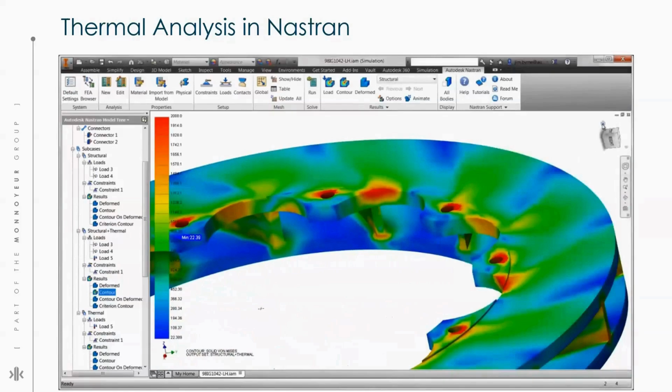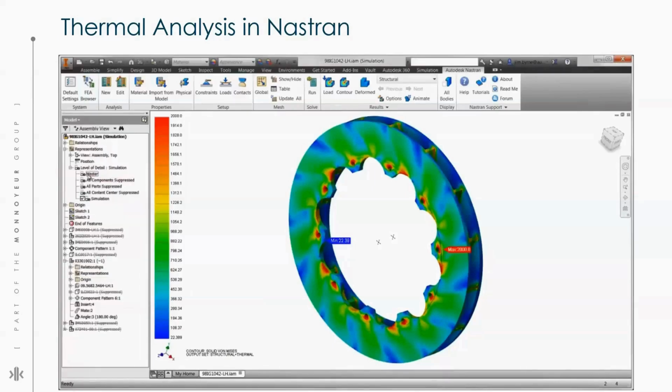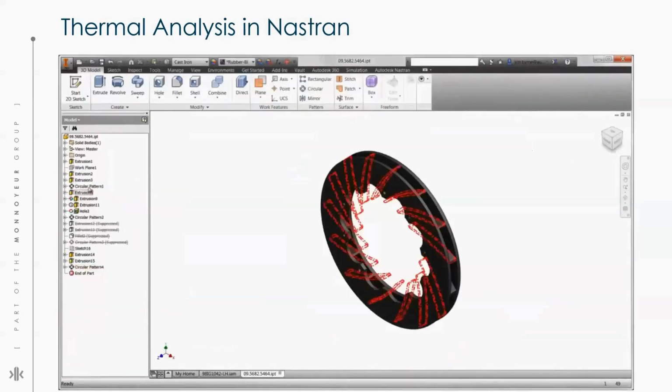The changes that we make here in Inventor can be reanalyzed right inside the CAD design environment. So you can directly switch your model from simulation workspace to designing workspace. There is no need to send the model back and forth between systems. Here we'll simply open the rotor in its own window and change the number of vanes we would like to use. So here we have added more vanes to increase the strength of your part.